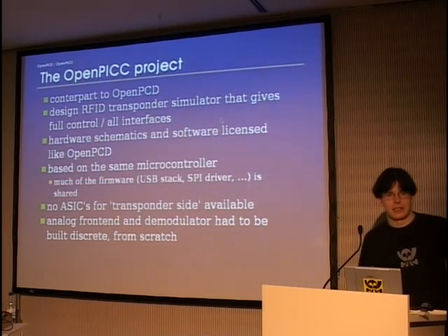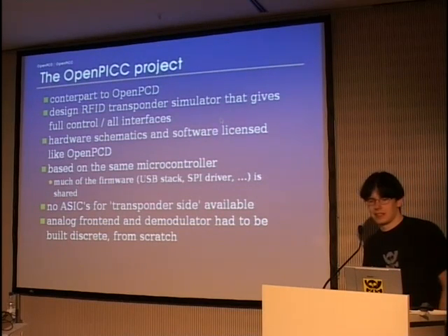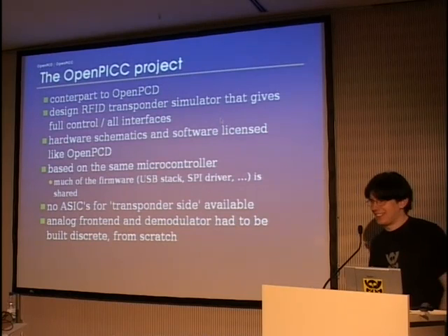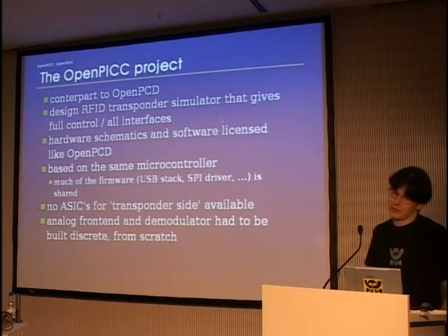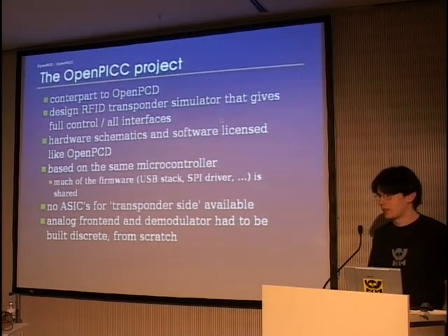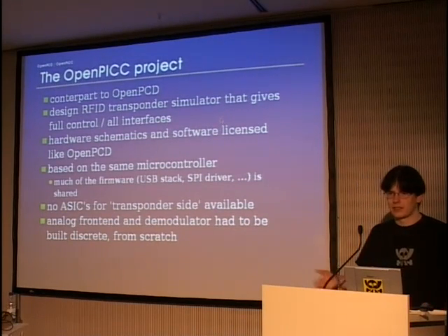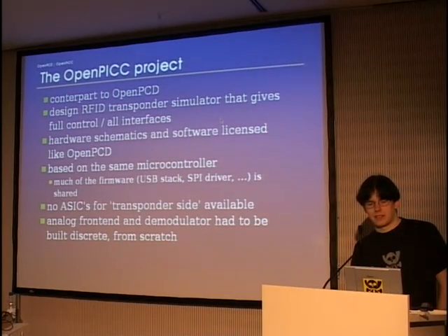Because those two projects are so closely related, in order to keep the development effort as little as possible, we reuse the same microcontroller, so we can use the same USB stack, the SPI driver, lots of the parts of the firmware, and also stuff like the device firmware upgrade and some host tools, so basically all that infrastructure has already been in place. However, there are no ASICs available for the transponder or tag side.